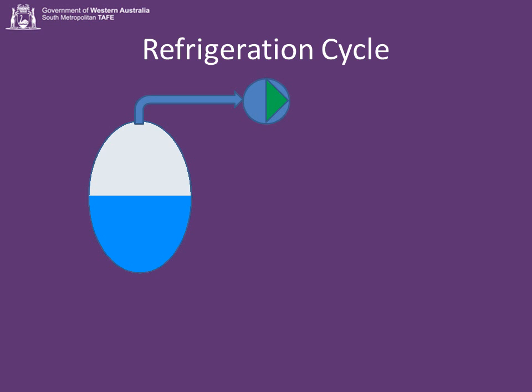Or, to put it another way, boiling point is a factor of pressure, and as pressure reduces, so does boiling point. So if you reduce the pressure enough, the liquid starts to boil. There it goes, boiling. Okay, now, the rules say that in order to boil, it has to have the latent heat of evaporation.